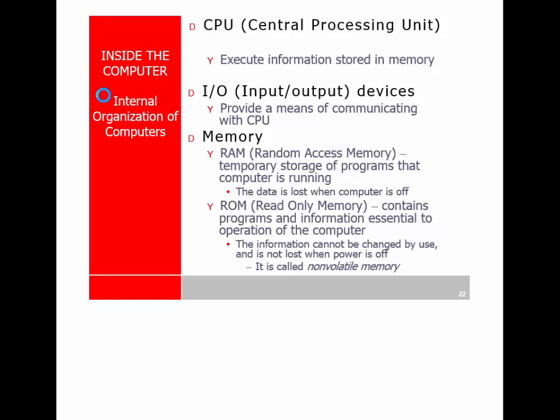Right there. That's an example of what used to be a very fixed type of ROM, and everybody in this room's not old enough to remember, but I'll just go back and talk about that. The early motherboards have a part of the computer that you can get to. It's called the BIOS. It's the basic input-output system, and it's stored on the motherboard. When the computer is designed, there's a chip on there that contains the basic firmware, and you'll hear the term firmware used a lot in this class.